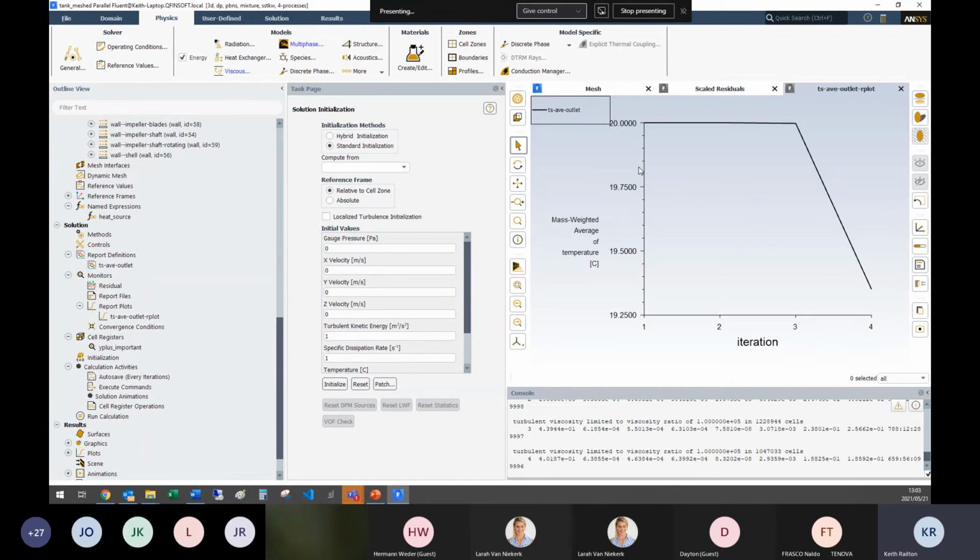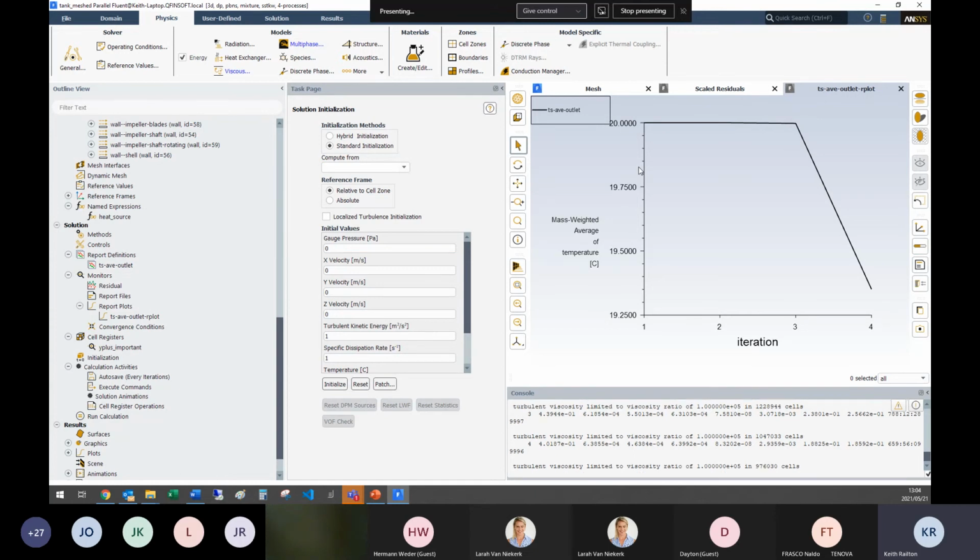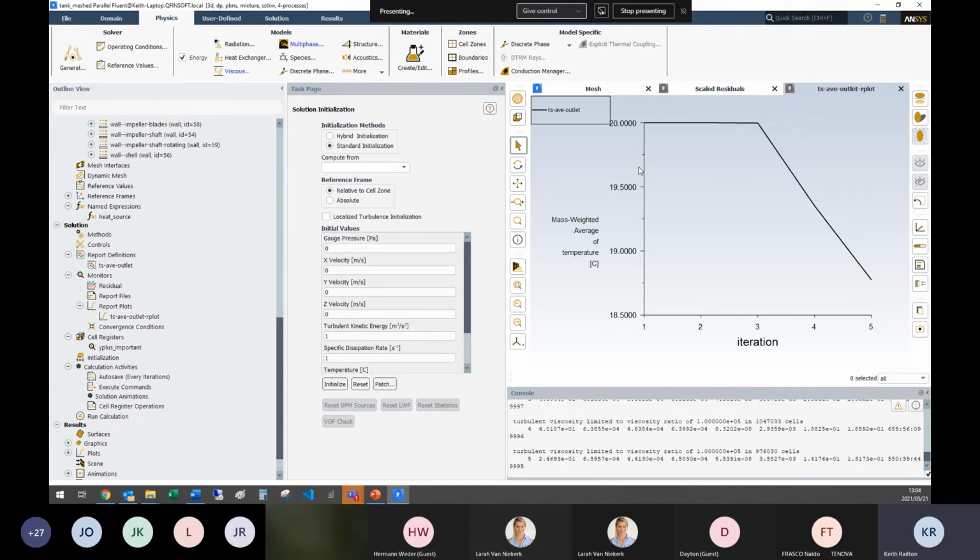Obviously you would need to add balance, momentum, and energy when you go from the one point into that region. That is all Fluent is doing in the background, inducing that source term. If you wanted to do it manually, you could do that using momentum and energy source terms, using a UDF, for example. So that is definitely possible.